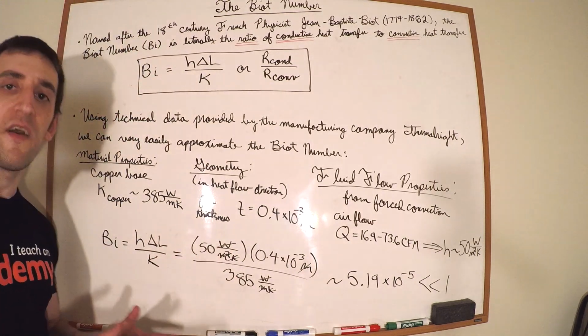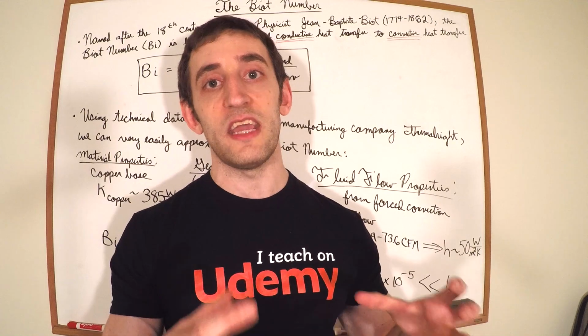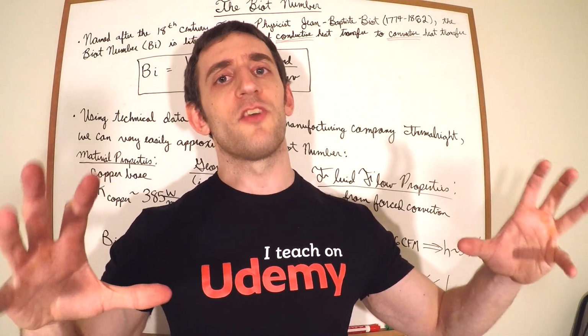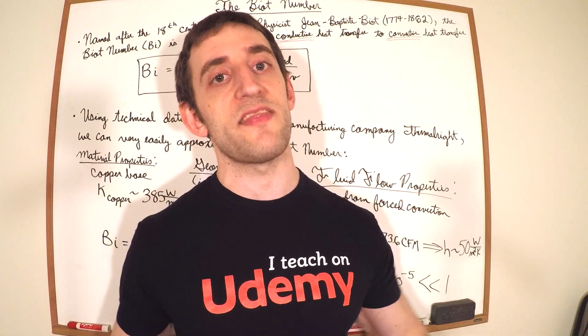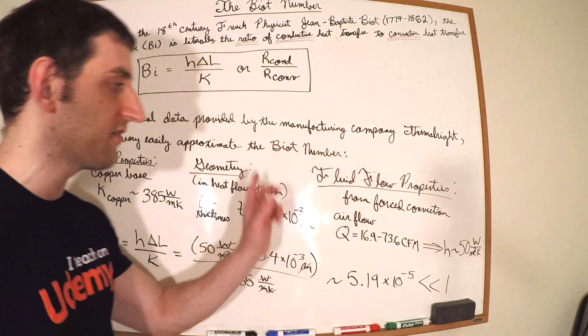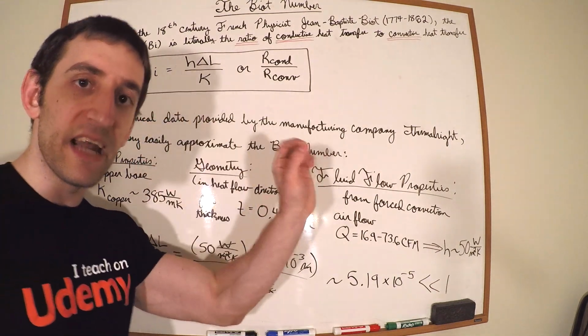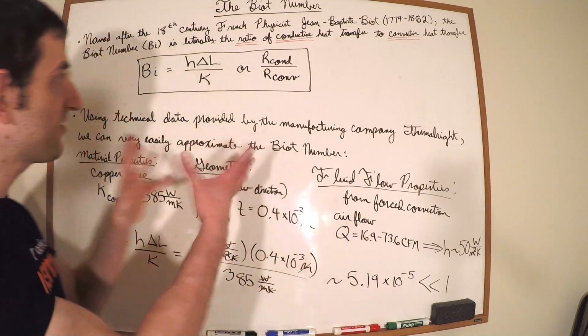If the Biot number is very small, that means it's going to be very high conduction in the object, but along its surface, the convection is going to be a bottleneck. It's going to struggle to dissipate that heat that goes throughout the object. But as a result of that, we get isothermal properties. We can eliminate coordinates. It makes our life simpler, okay? So that's the Biot number.